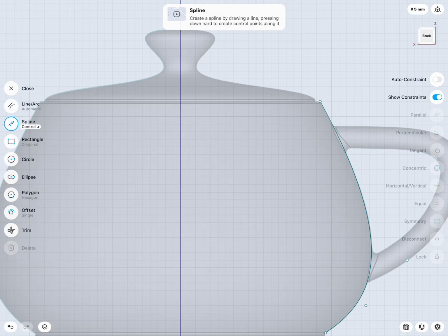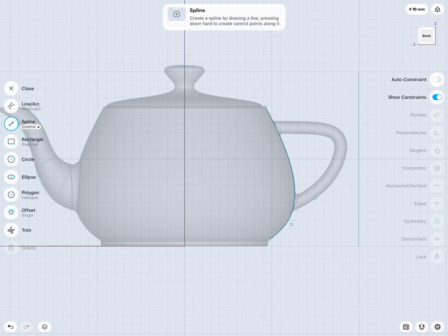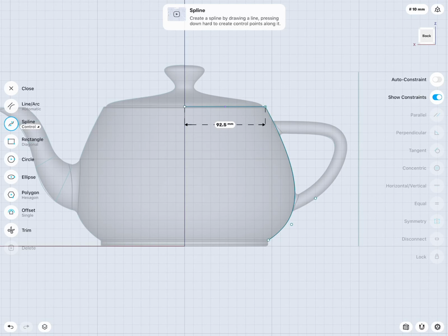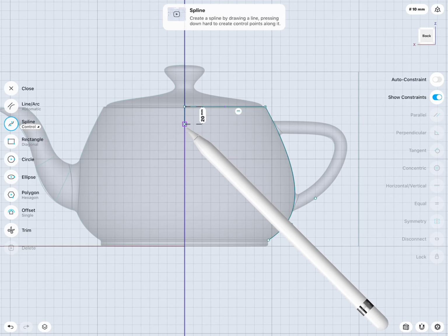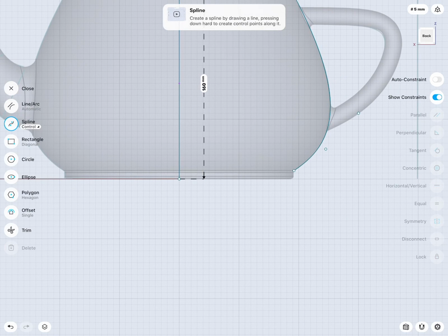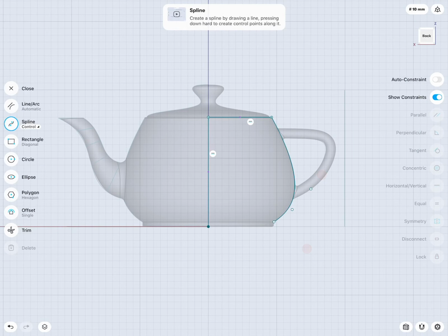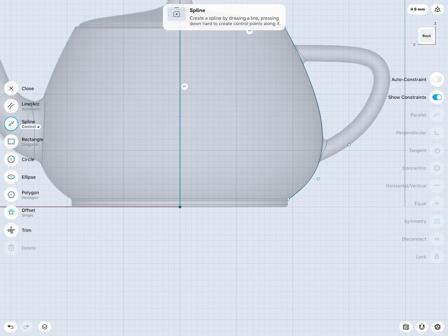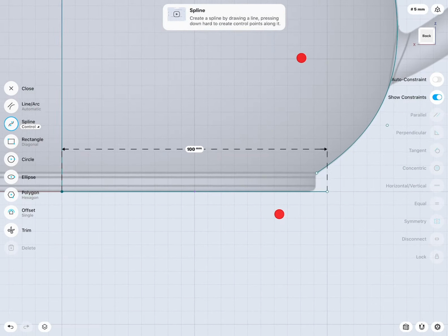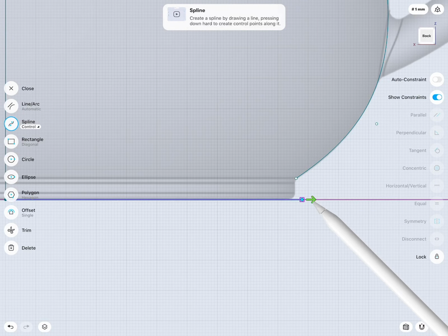Okay. Now for a revolve, we need a full sketch. So I will draw a horizontal line, make sure this remains horizontal, and draw a line down to the bottom. Also here, make this vertical. This point we can even lock, so this is going to be our center axis and can't move anymore. And draw one line to the right. Let's move this back a little bit.